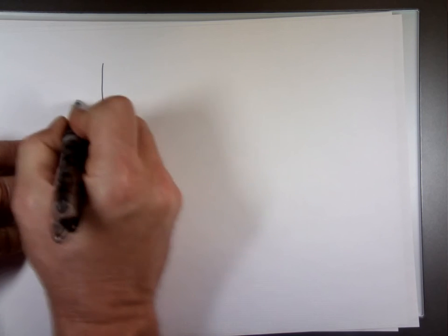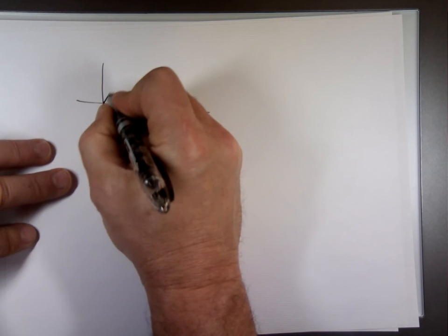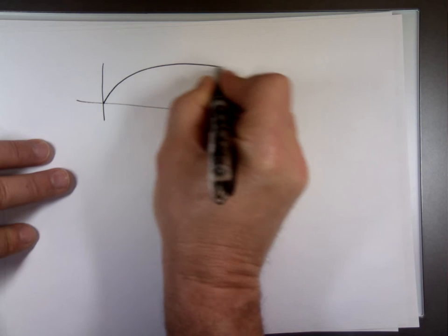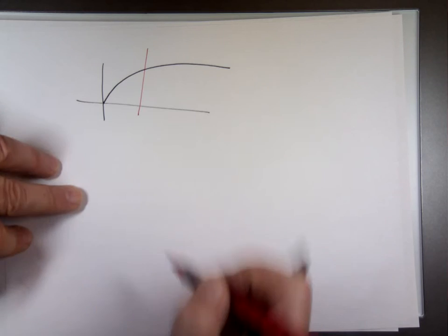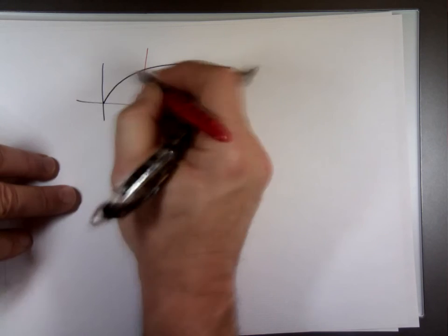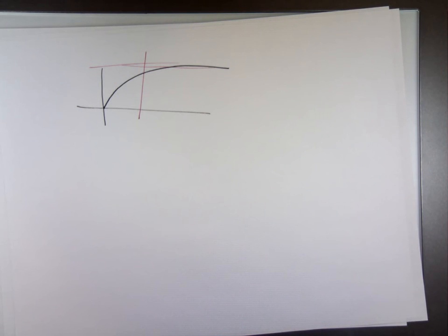This is what happens in that example. It says assume the inductor reached steady state. That means you pass this point. When you're rising, your voltage is changing. Once you pass that point, notice your value is almost constant. So that inductor starts to react as a source and is going to supply the power. The same thing with the capacitor.